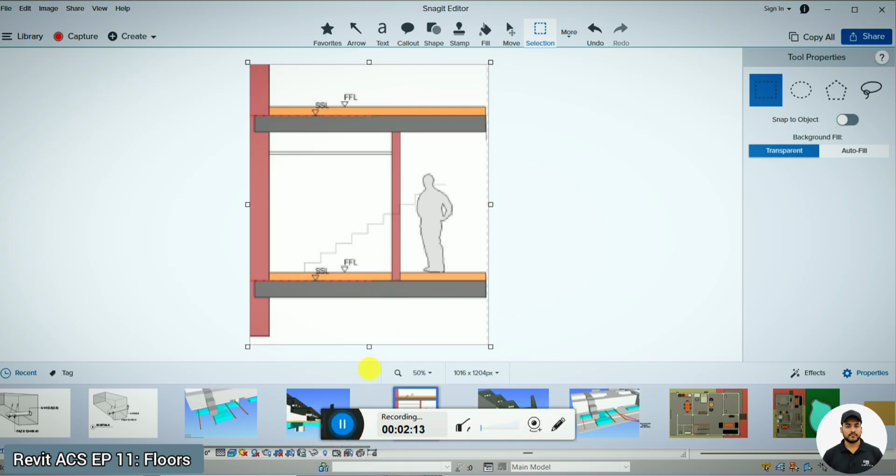If we have a kitchen area or toilet area, then the architectural floor depth will be more, so that the MEP services can run inside the architectural floor, because we can't penetrate the structural floor, which is made up of concrete plus RCC. It is the strength part of any building, so we can't penetrate or damage the structure. In the architectural floor, we can run the MEP services, and after that the final finish will be made up of tiles or marble, whatever the client or project requires. So you are clear about this.